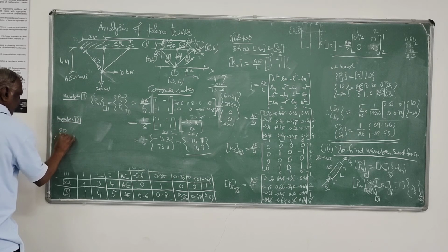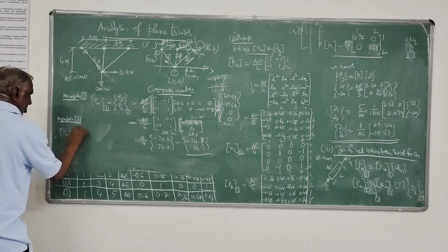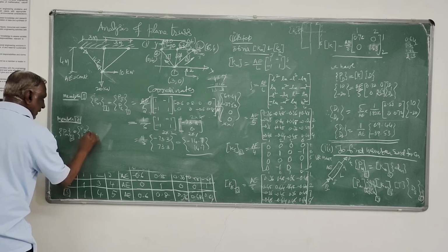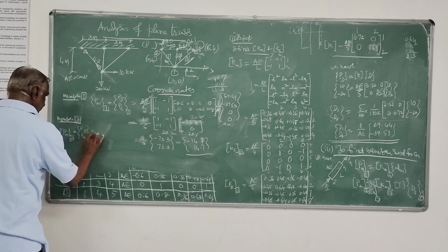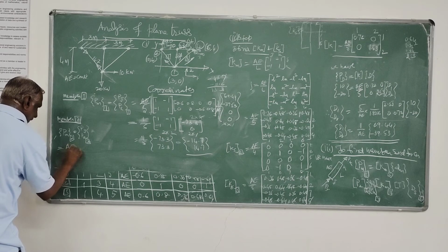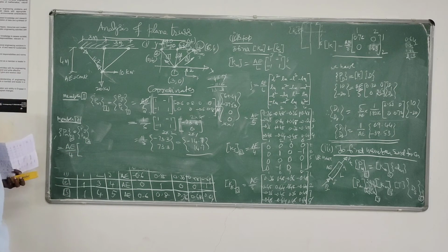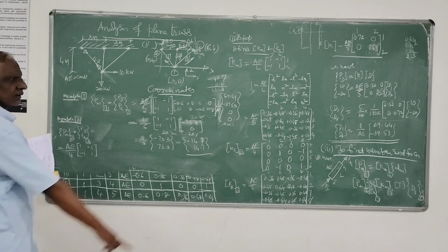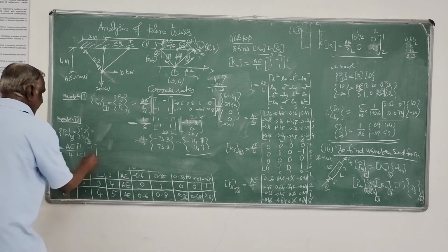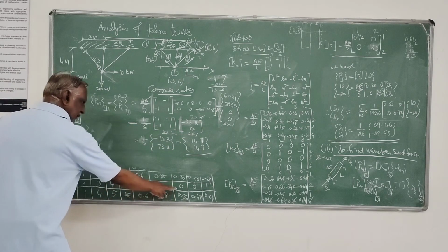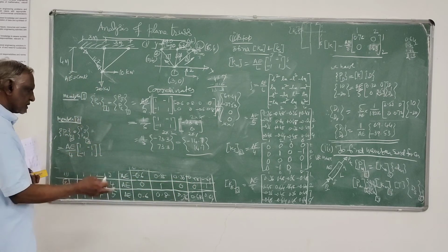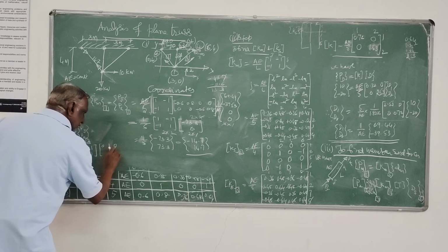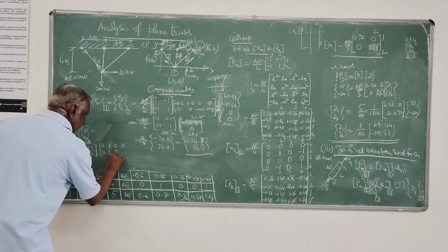Member 2, that is PM2, again two forces PJ, PK of the second member, is equal to AE by L, AE by 4, L is 4. So 1 minus 1 minus 1, 1. That is Km into T. T of that member is L, M, 0, 0, 0, 0, L, M, where L is 0, M is 1, so 0, 1, 0, 0, 0, 0, 0, 1.